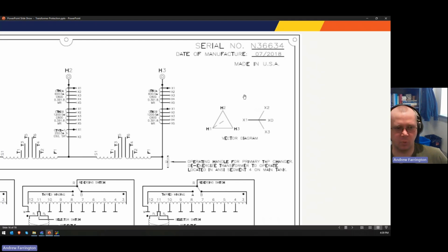I think I've only worked with one utility that had a negative sequence rotation for their system, not like a particular transformer or whatever, but their whole system was negative sequence. So they had a 3-2-1 sequence for all of their stuff. So I needed to certainly account for that in the relay settings I provided for them. But I've only seen that the one time. So if not defined, I would assume that the system sequence is positive.